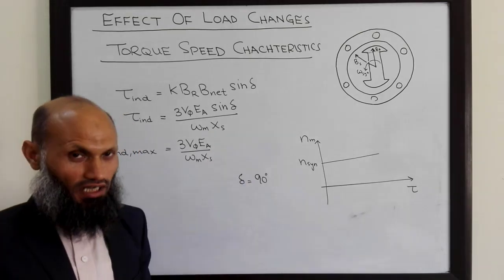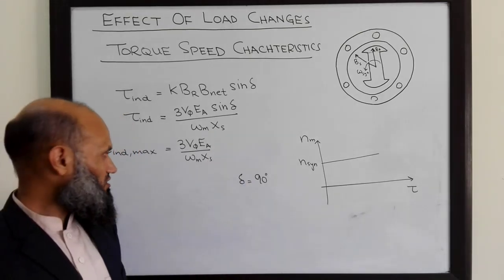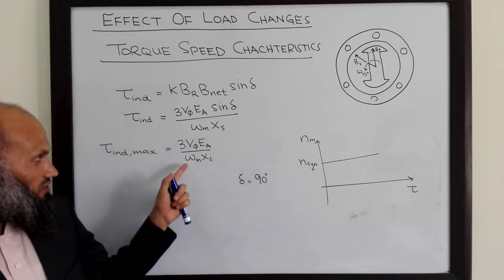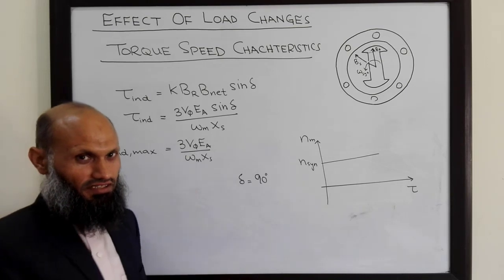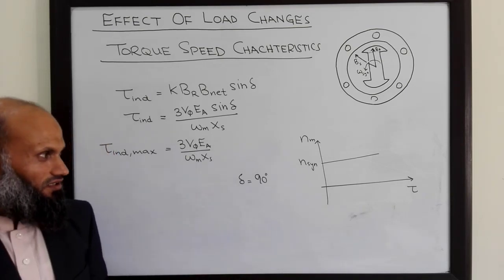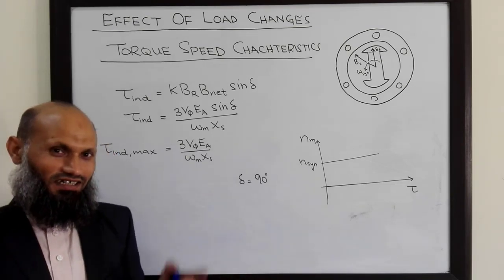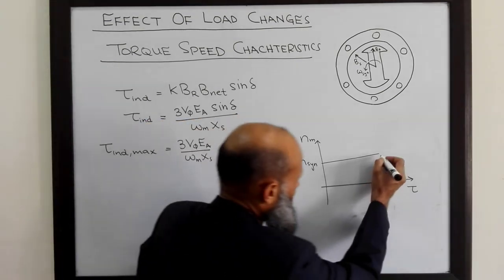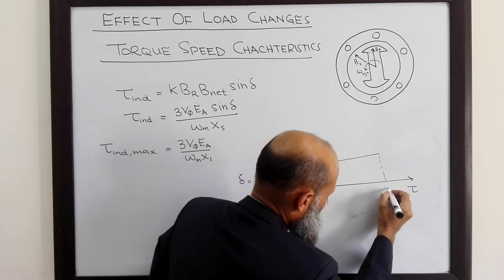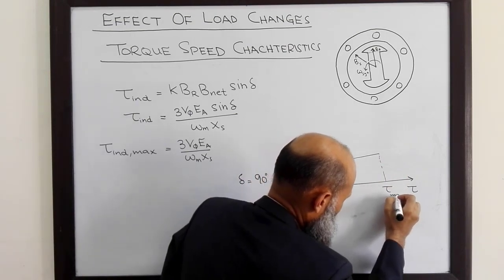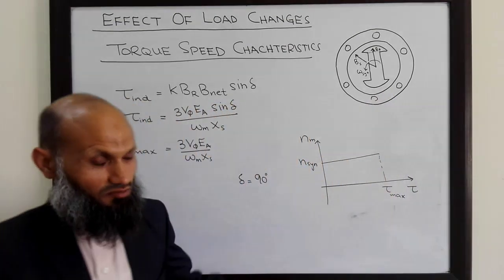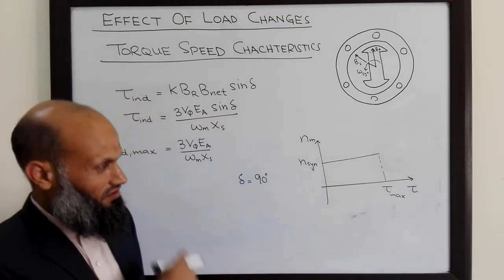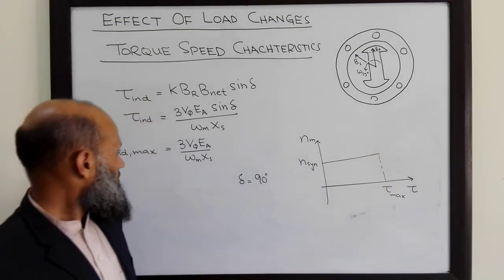Rather, there will be high vibrations in the synchronous motor, and that will damage the motor. Why vibrations? We shall talk about this point in more detail when we talk about starting problems with synchronous motors. If the load torque increases beyond this maximum torque, the motor will just stop, or rather be damaged.